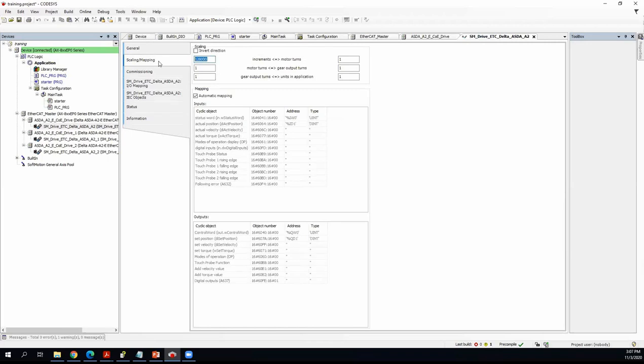So this is the resolution of the servo, and it means that for one turn, we need to send this many pulses to the servo. This is the resolution of the encoder, let's say, for input. If you would like to turn it once, you need to send this value to the servo. If you need to turn it double, then double of this value.